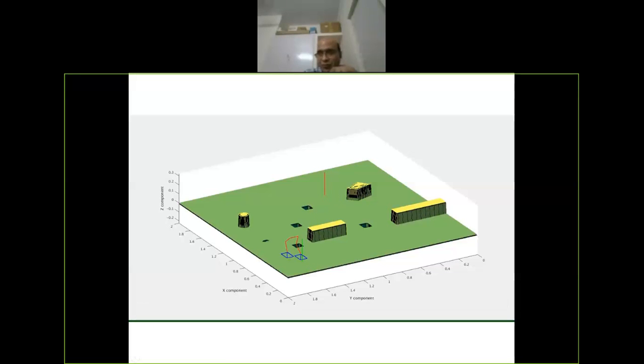Okay, so these two terms are sometimes used interchangeably, but they're not the same. One is path planning, just to find a path to go from one point to another point without hitting an obstacle. The other is how to follow the path exactly. Okay, and that is what is called motion planning. Motion planning is at the joint level.